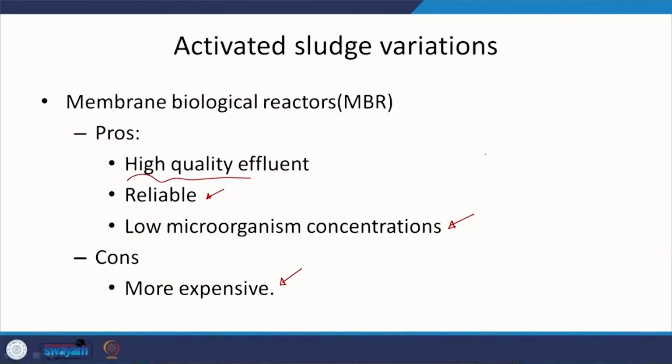Due to different kinds of precipitation or microbial growth, you are going to have fouling, as in not enough pore space, if I may say so, or pore area for the water to go through, right? And thus you are going to have to apply pressure, which again means higher cost or less flow rate. So maintenance is an issue depending on how well you are running the plant.